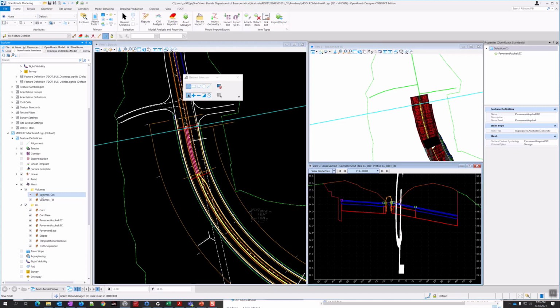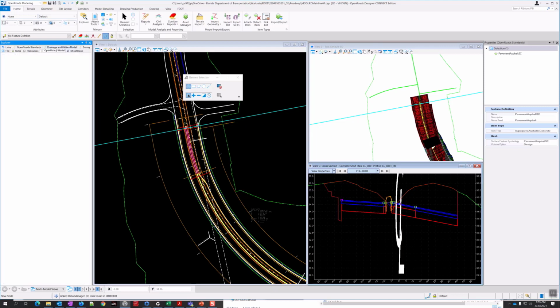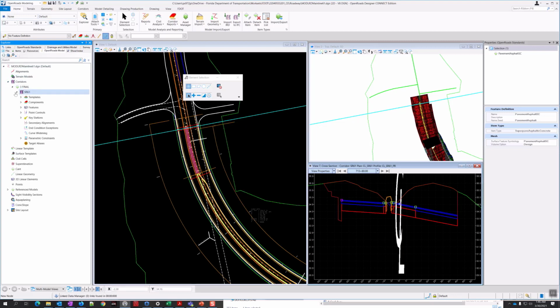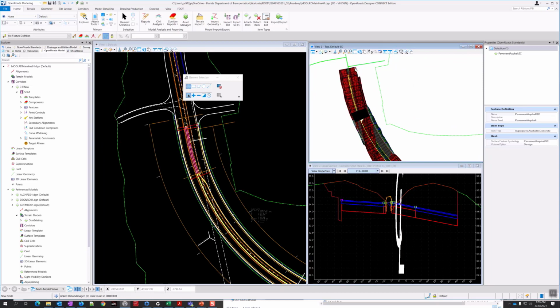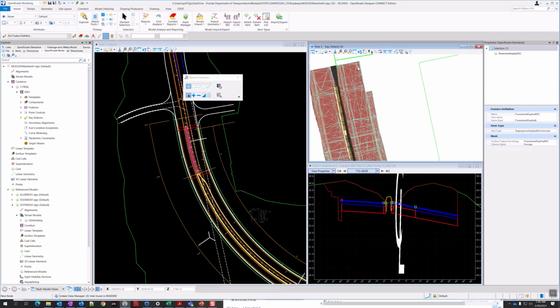I can see it under standards, but most of the civil geometry shows up under OpenRoads model. So if you've used this at all, you kind of get used to, okay, I can go to corridors under here, and my reference model should show my terrain models here, but there's nothing else. There's no volumes here, so I can't just go in here and delete it. So if you need to delete it and redo it, you just need to go into the 3D view, the only place you can see it. Just grab the triangles, select it, and delete.